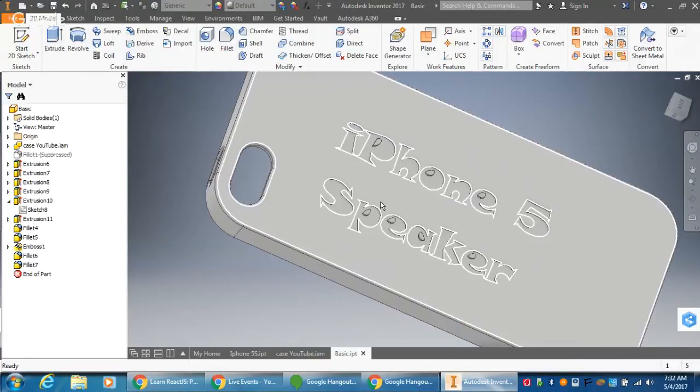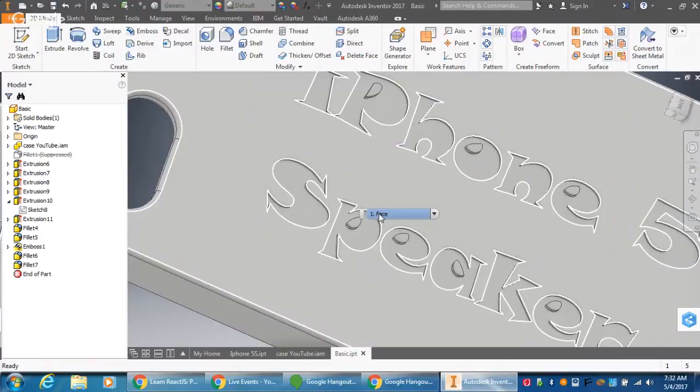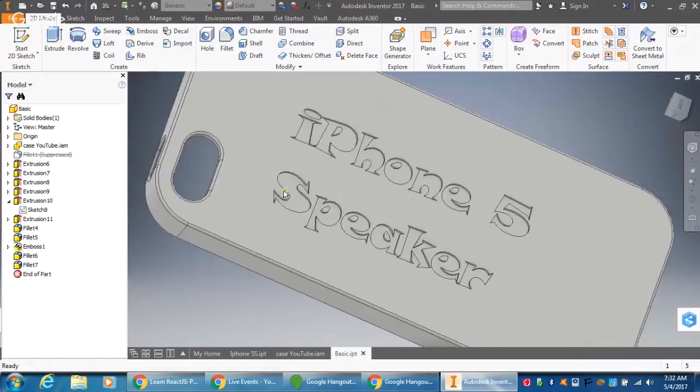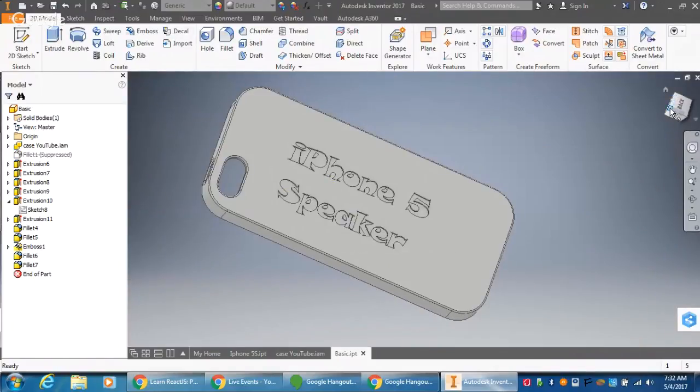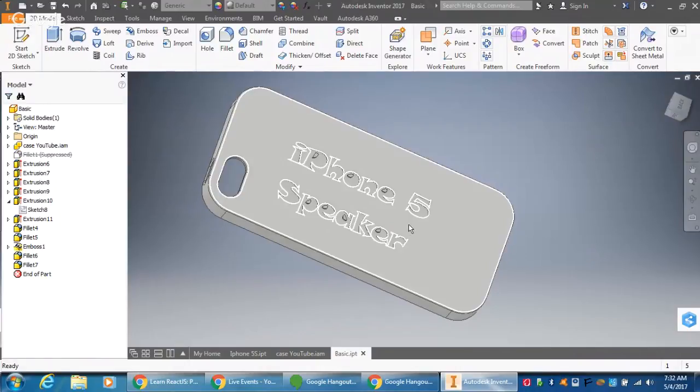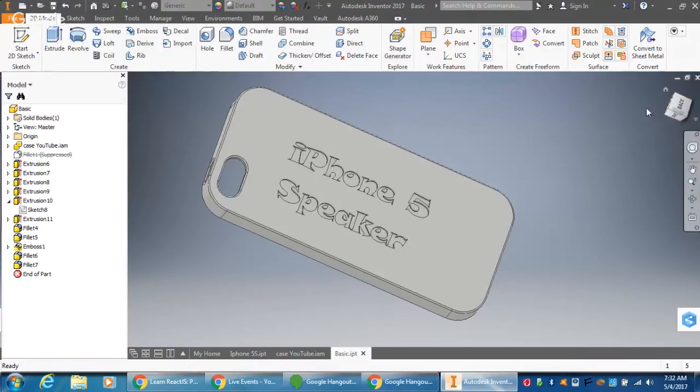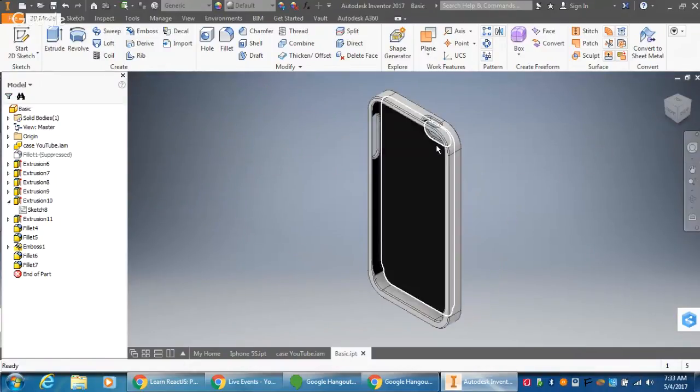You have to remember that a standard sheet of paper, we'll just call it, 2 sheets of paper is about 5 thousandths thick, something like that. So you can go 5, 10 thousandths thick on each of your layers as you cut down into your cell phone case. And I think we have it about 100 thousandths thick, the case itself. Even if you go 10 thousandths thick, you can get 10 different layers of depth in your drawings, and you can do some pretty intricate stuff. So that's going to be up to you.